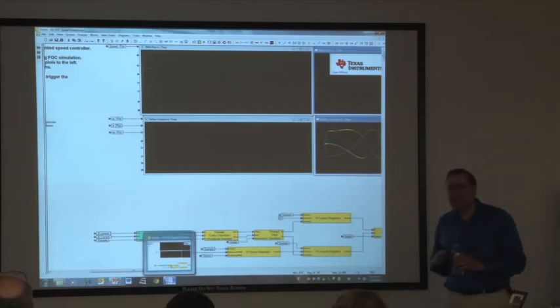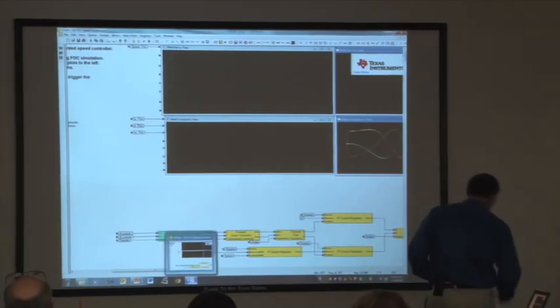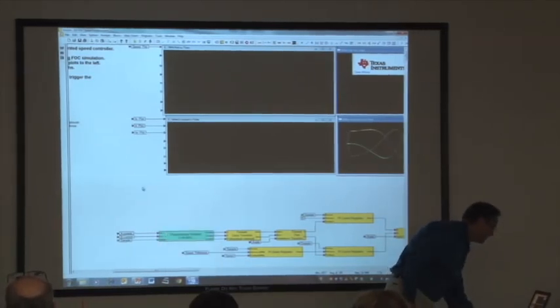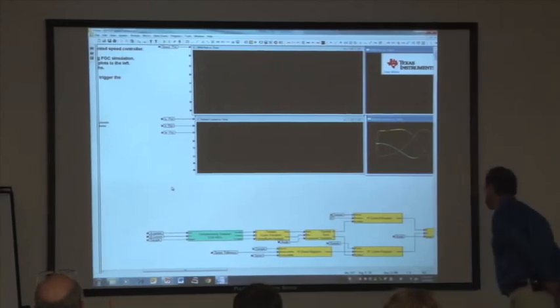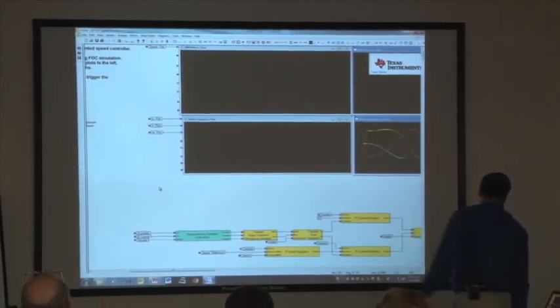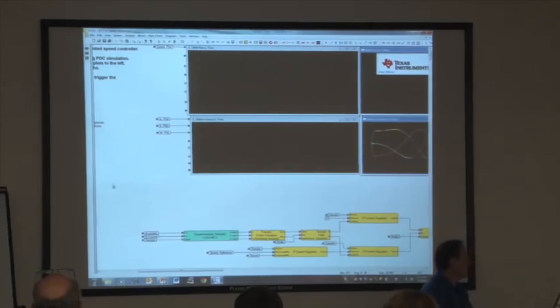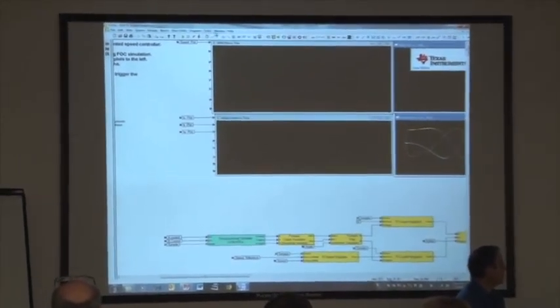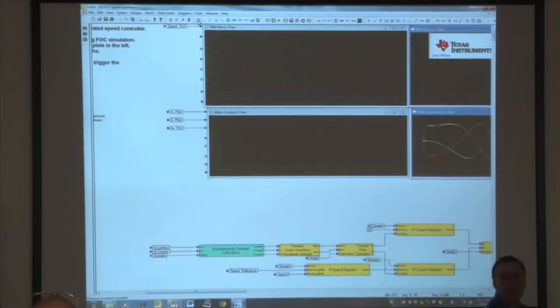On the reference, I pulled down the variable, and I think I named it 0. How do I set a value to 0? At least in my case, it's right under the tools part of the toolbar. There's a little block which has a red 1 in it. Depending on your screen resolution, it might be somewhere else. You click on that, drop it into your simulation, and then double-click on the 1 to change it to a 0.